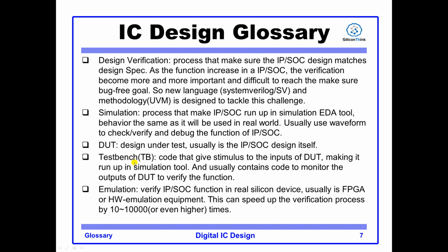Test bench. A test bench is a code segment that gives stimulus to the inputs of the DUT and makes it run in the simulation tool. And it usually contains code to monitor the output of the DUT to verify the function.